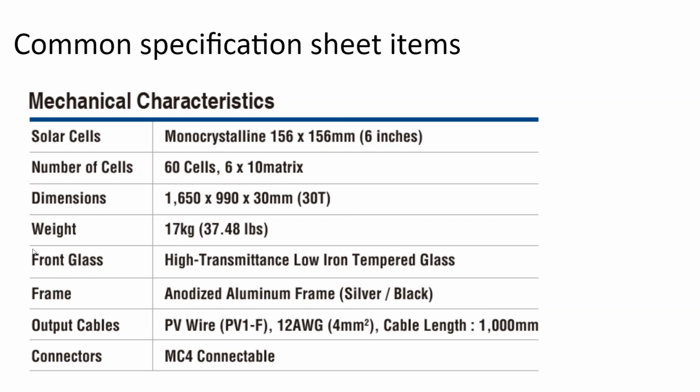So we got our first mention of PV wire as the output cable. And look, these output cables from the panels themselves are number 12, but most in the solar industry are going to step up at that point into number 10, sometimes number 8 to transition home.